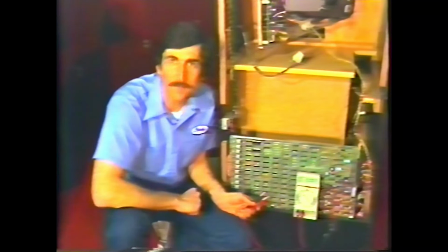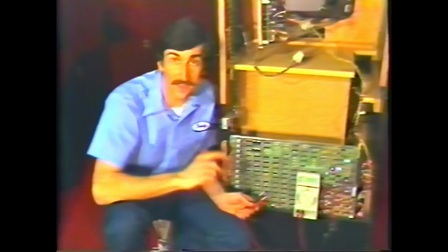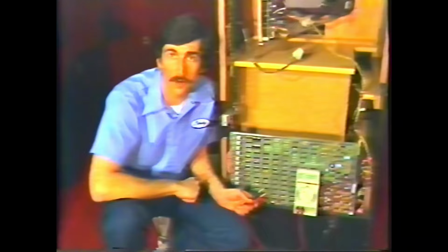Well, even if your game doesn't have 5-volt test points or ground test points, there's still a real easy way that you can check the 5 volts going to the computer board. Do you see how all the integrated circuits on the board are arranged in rows? And do you see how there's this heavy printed circuit board trace running up and down each side of the rows of chips? Well, one of these traces, or power rails as they're called, carries the 5 volts to all the ICs, and one carries the ground. By placing the meter leads across the power rails, we can read the voltage directly across it. And here we see that it's real close to 5 volts.